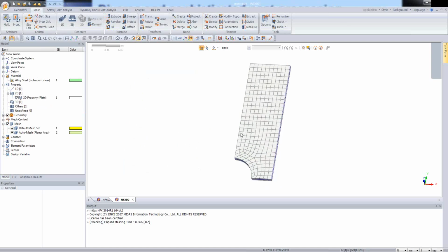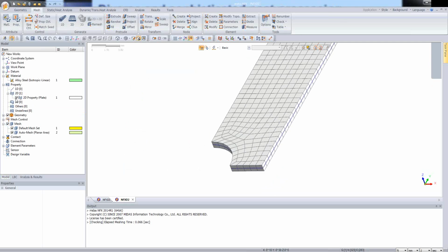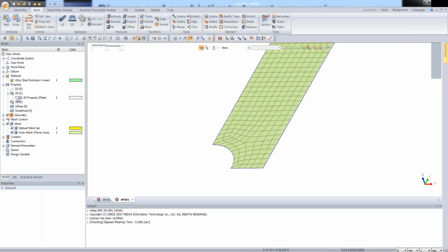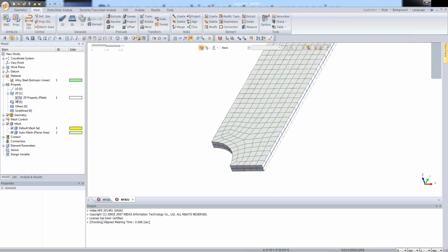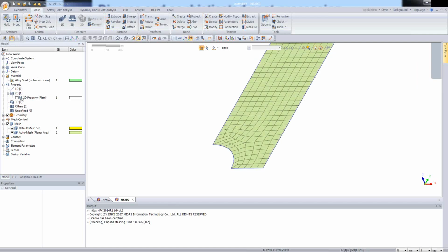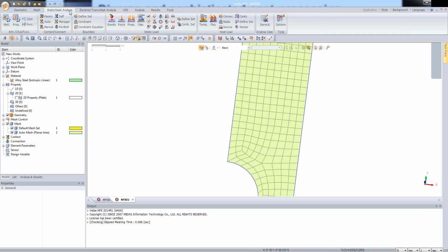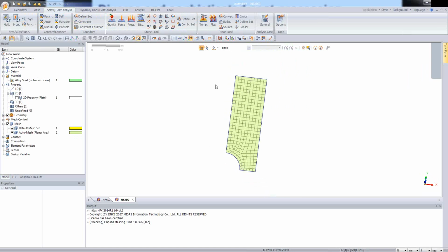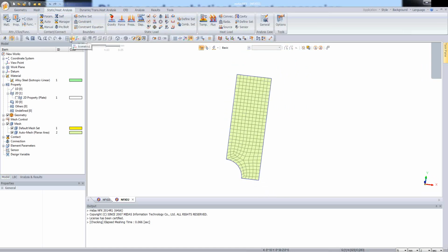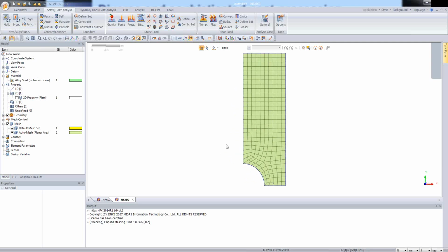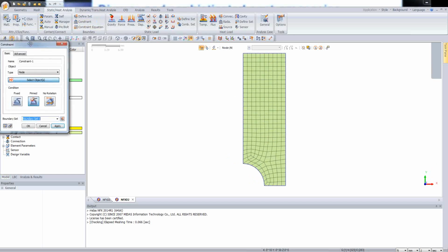We can also display the thickness. So now I'm hiding and displaying the thickness for the 2D plane element. Okay, so done. Now let's go to the static and heat analysis step, and let's assign the constraints, and we will use the feature of the symmetrical condition. So now I'm clicking normal to set up the view, and I'm clicking on the constraint.